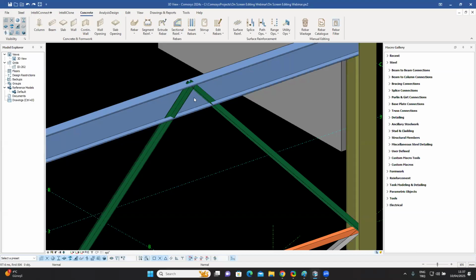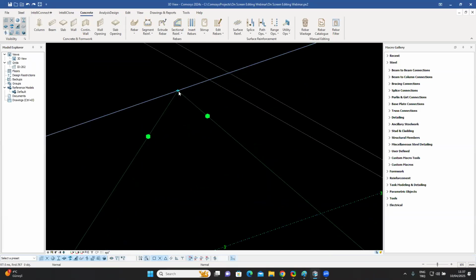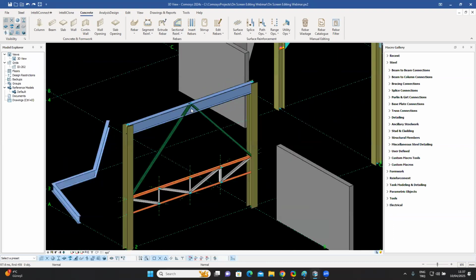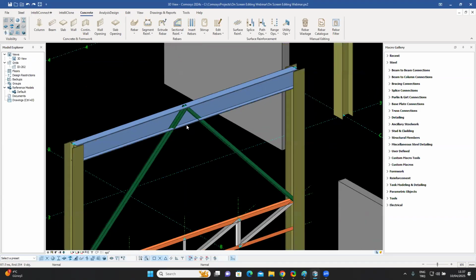But the problem with this is if I enter it at the middle of the beam, then the finite element model, which can be seen by doing, for example, Alt-D, is connected at the moment. But if I move the braces down physically, the finite element model will be disconnected. I don't want to do that. So I have another handle which doesn't change the formal finite element model, but moves or offsets the frame